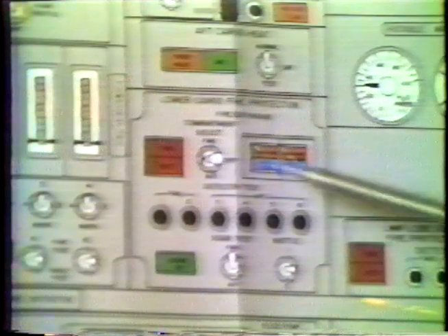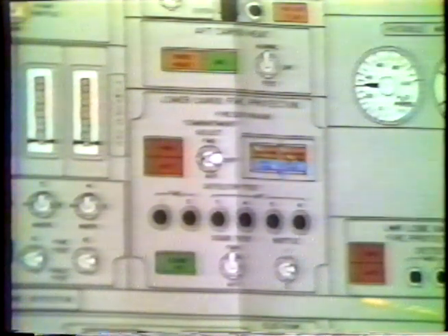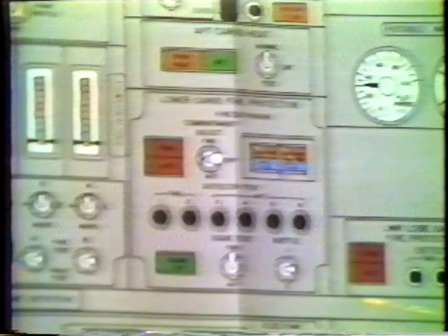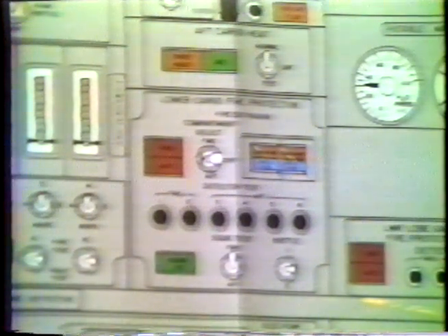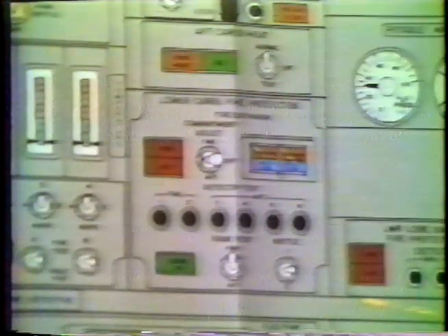Normally the switch is in the off position, and when the switch is moved to the forward position, what it does is arm the bottles for discharge to the forward cargo compartment. It also cuts off the air that's going to the forward compartment in flight. It'd be the same as moving this control valve to smoke. The main reason here is to reduce the amount of air that's going into that cargo, so when you do fire the Freon, the concentration of Freon remains at a high value for a long period of time.